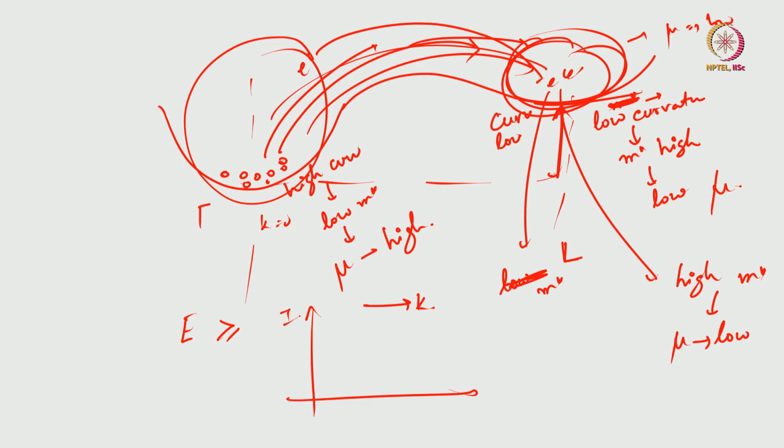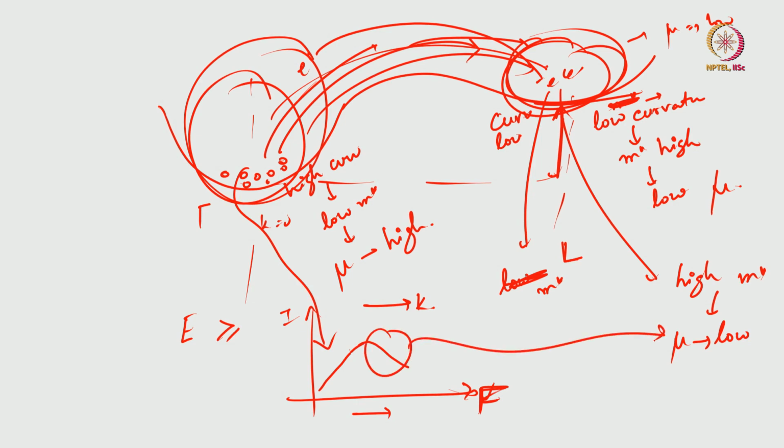So, you had a current, you had a voltage, the voltage is the same as the electric field, by the way, so you can plot field here. Initially you will get current, because only this valley is participating, but at one point when electrons start going to the other valley, the current will start decreasing, because this is where suddenly the mobility has become low. Eventually you will again rise here, because you will go to a steady state where you are now putting in sufficiently high electric field.